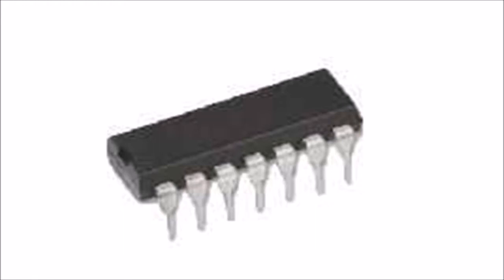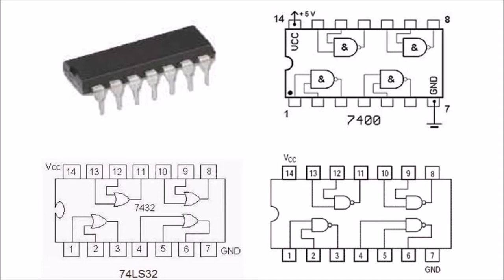Generally speaking, the TTL logic ICs use NPN and PNP type bipolar junction transistors, while CMOS logic ICs use complementary MOSFET or JFET type field effect transistors for both their input and output circuitry. As well as the TTL and CMOS technology, simple digital logic gates can also be made by connecting together diodes, transistors, and resistors to produce RTL, resistor transistor logic gates, DTL, diode transistor logic gates, or ECL, emitter coupled logic gates, but these are less common now compared to the popular CMOS family.